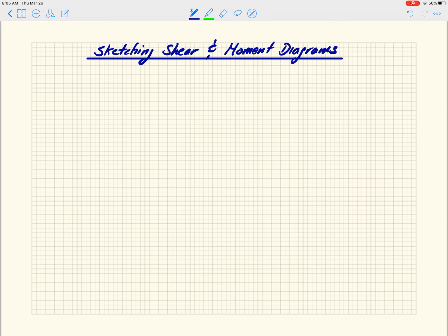And if you don't have any expectation about what the shape, and the relationship between shear and moment diagrams should be in those particular cases, then you're going to struggle to validate those models and error screen them and correct any issues that you have.